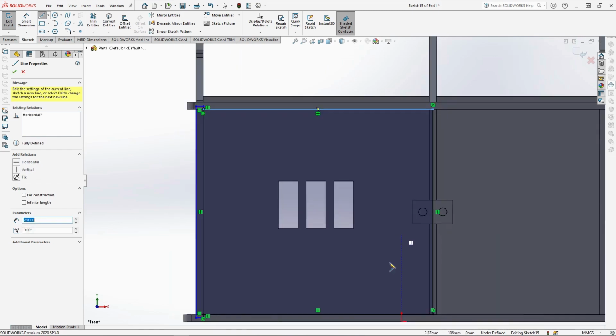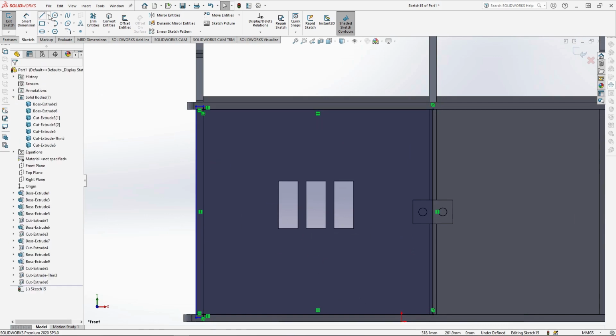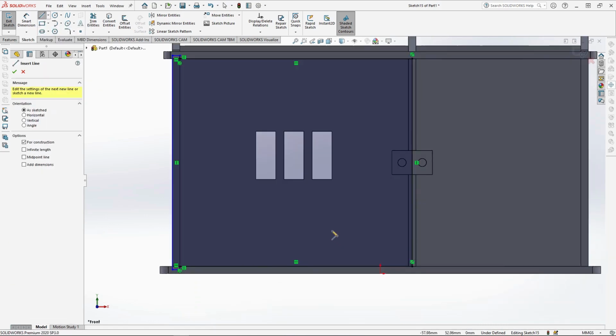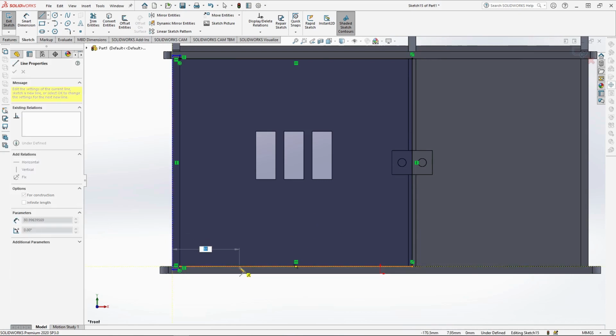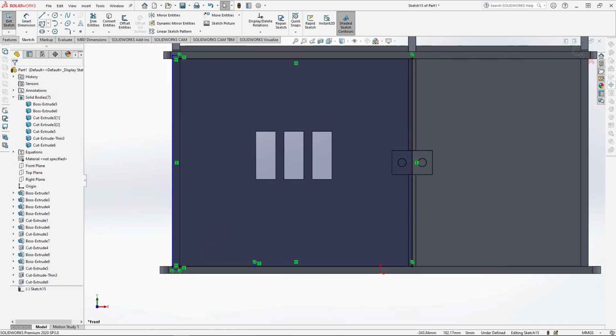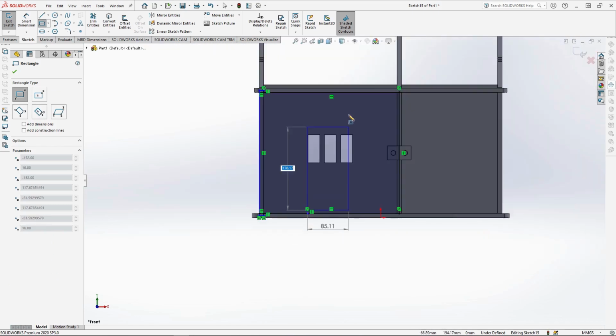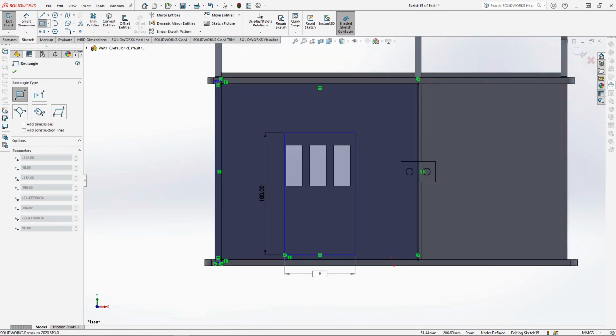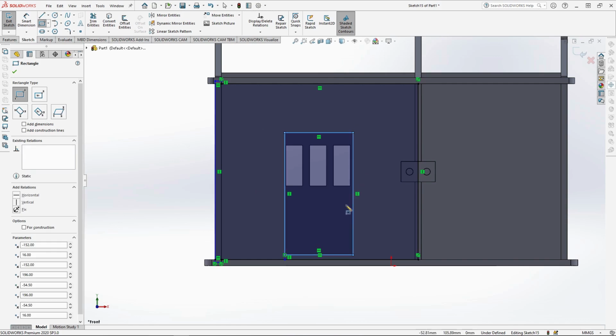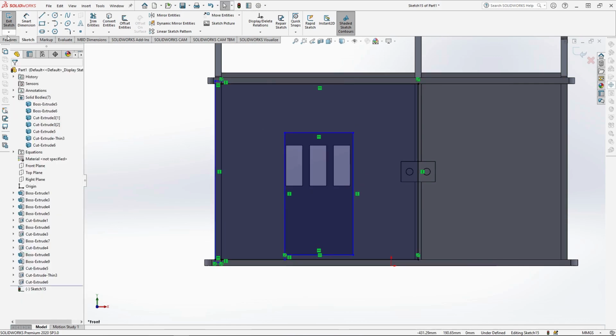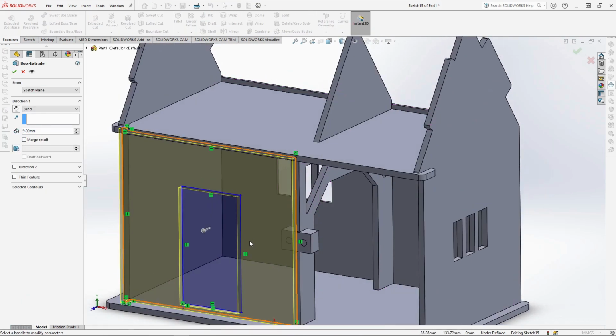For the doll's front door, we're going to need to add a hole for them to go into. Use the centre line to draw guides for where to start it. Sketching from the corner along the base panel, go inwards 99.5mm and up by 7. Then take the corner rectangle and draw 180 by 97.5mm doorway. You can then extrude this by 9mm unmerged.